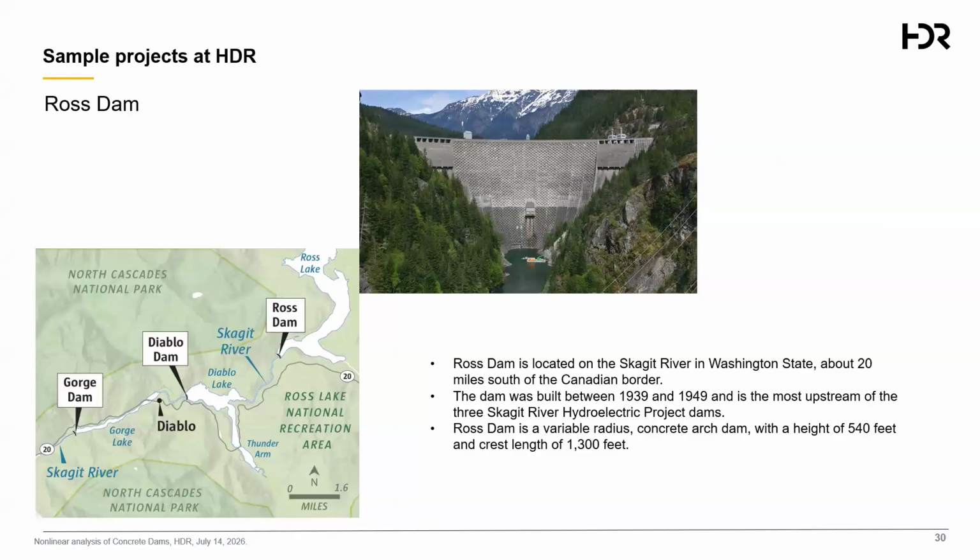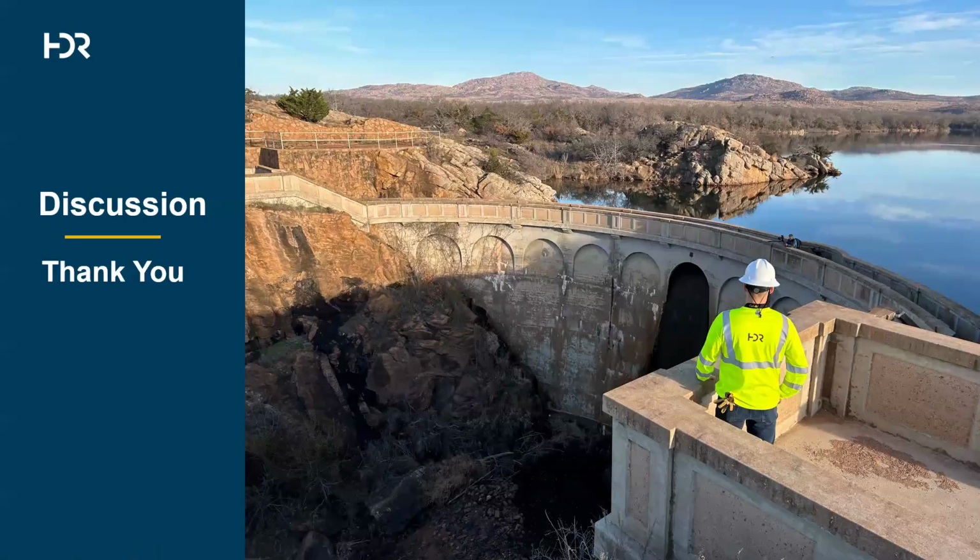So meshing affects the results quite significantly, and if you don't properly mesh the geometries, what happens is under large deformation, the mesh may distort in a way that the software gives you an error. So you need to have a very clean mesh, meaning the aspect ratio of elements is not too high. For example, if you have elements that are too long but the thickness is small, they are more susceptible to mesh distortion during analysis. So you need to make sure your meshes have similar aspect ratios.